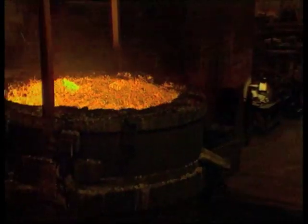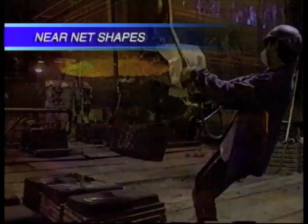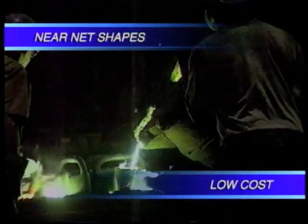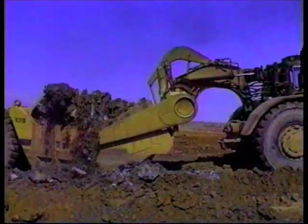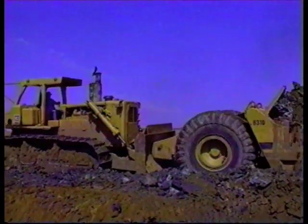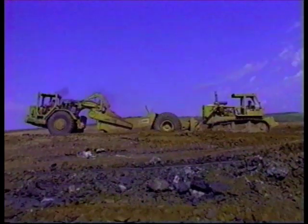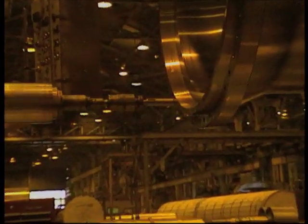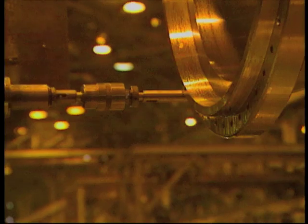Today, 250 plants produce 1.5 million tons of steel castings each year. Today's design engineers use steel castings because they can obtain near-net shapes with the properties of steel at relatively low costs. For many parts, the only economical way to make the shape is to make a casting. With a steel casting, you get the high strength, toughness, and impact resistance of steel, which is not available with other materials. Abrasion, impact, and wear-resistant steels are easy to cast. They are difficult to fabricate or machine from bar stock.